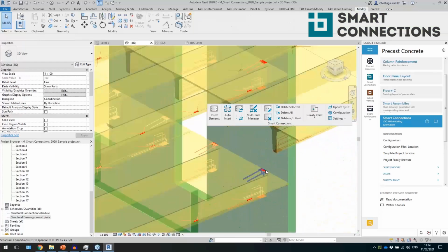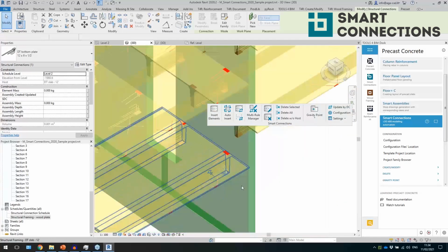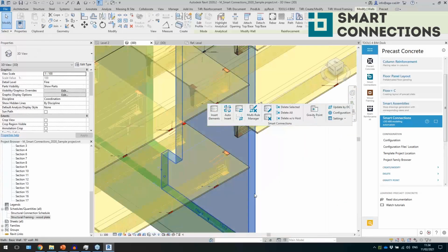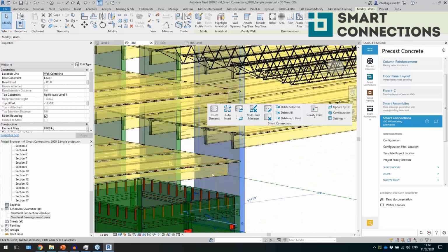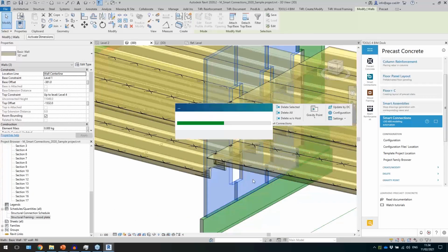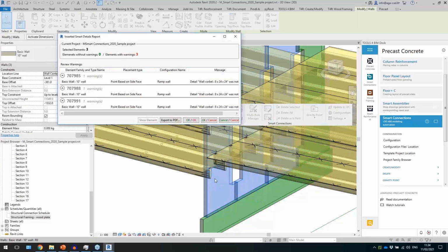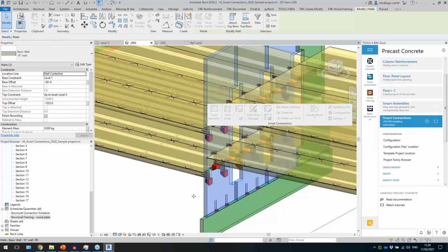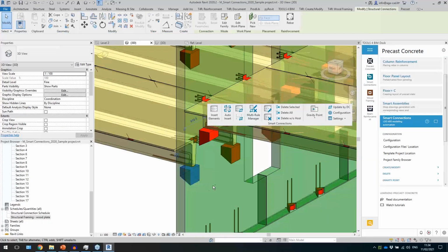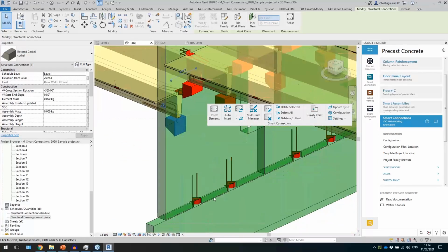So I have something in my structural framing elements, just placed at the stem and on the sides. And then let's do that for the walls. Okay, and auto insert. So what will happen is that it will also place some corbels at the position of, basically again, almost like at the position of structural framing elements.